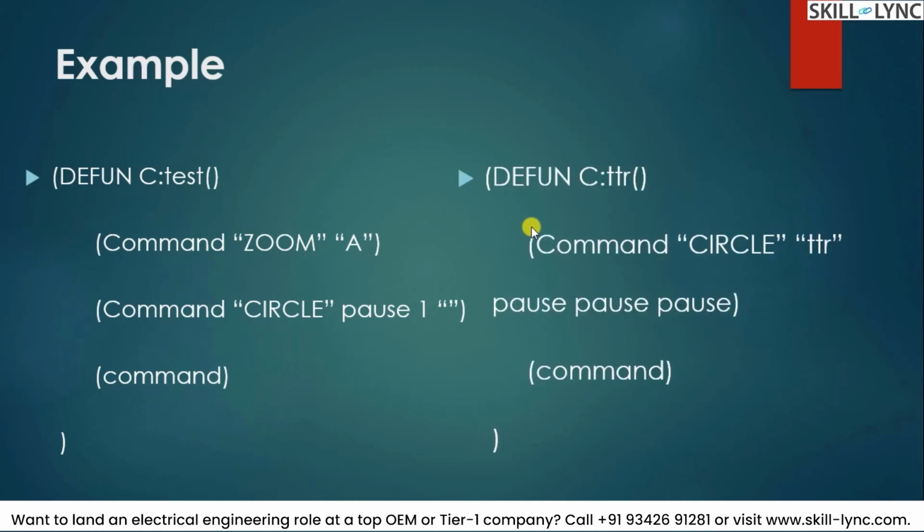Likewise, one more example is a very popular one that we can use. If you could recollect, in the circle command itself, we have the tangent radius option that does not bear any system variable. That is, you cannot call it directly. You have to go in a sequence to specify explicitly using the GUI interface stating that it is going to be a tangent radius. Whereas we can use a custom command in this AutoLISP environment to create your own function called TTR.